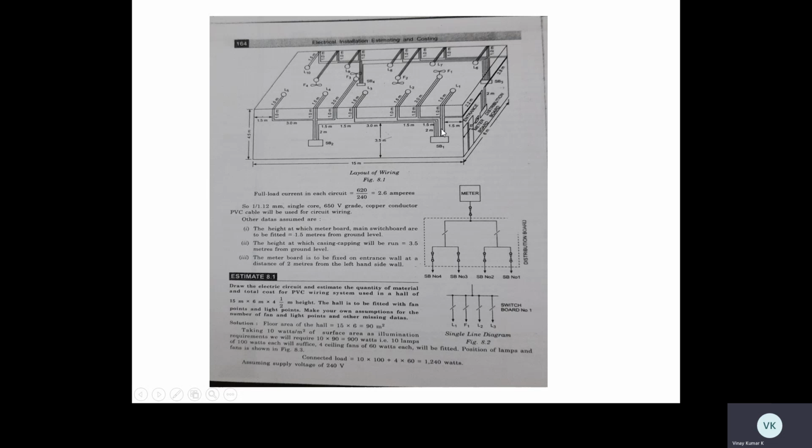Okay. I have got this phase wire till switchboard 1. See here, this is the length of the cable which I am showing here. This is the phase wire. One wire goes to SB1 and the other wire goes to lamp 1. SB1 to lamp 1, SB1 to fan 1, SB1 to lamp 2, SB1 to lamp 3, SB1 to SB2.